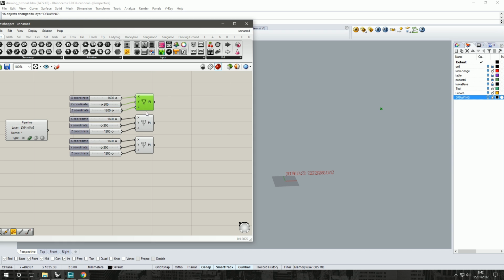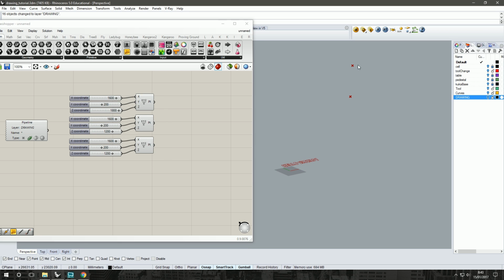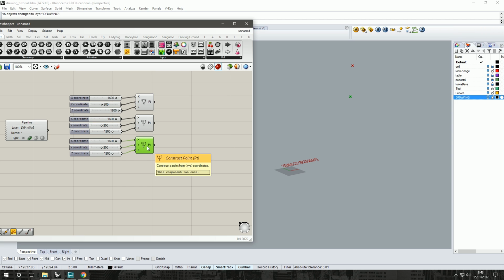So now we'll keep our sort of bottom left corner in the middle. Then we'll move up in the Z direction. Go to 1800. So there's 1800. There's the top left corner, which if you look down here, it would be about here for our import area. And for our bottom right, we will bring this minus 800. So that means we've got a canvas that's 600 tall and a meter wide. So a lovely large piece of card.